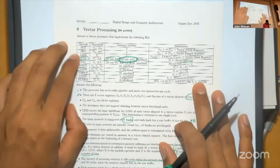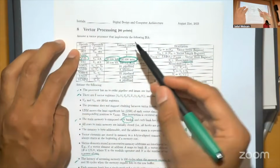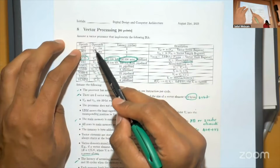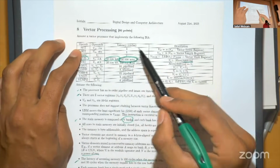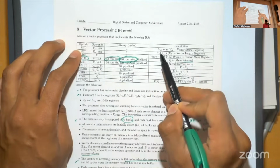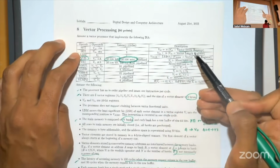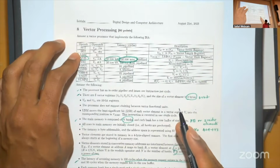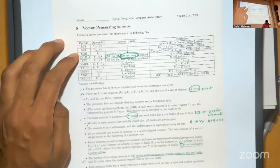So the first one is set. What this does is you have two operands, VST and a number n. It takes one cycle. And what you can do with this is you can write n to VST. VST in this case is the vector stride register. Essentially, what is the stride that I'm going to use to access the memory for whatever array that you want to access.